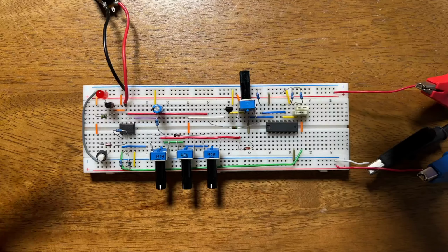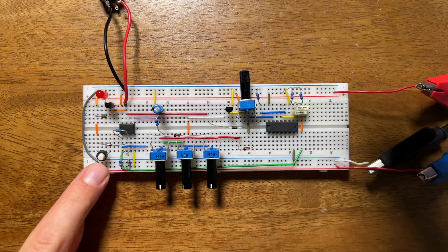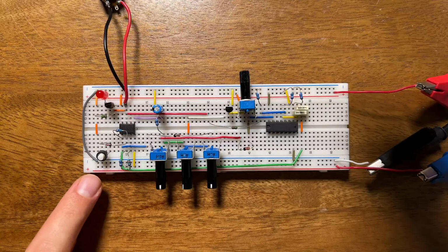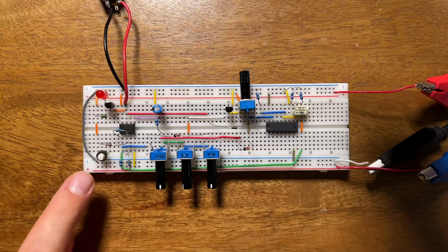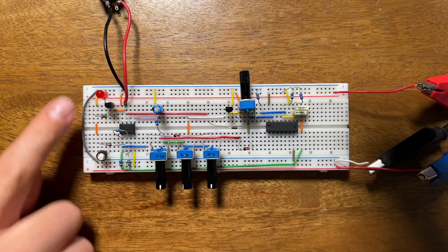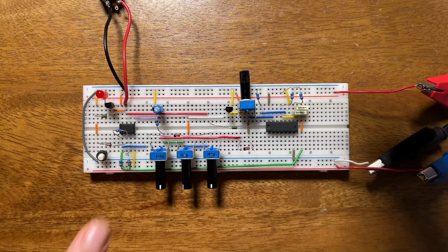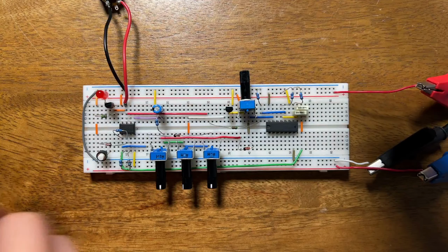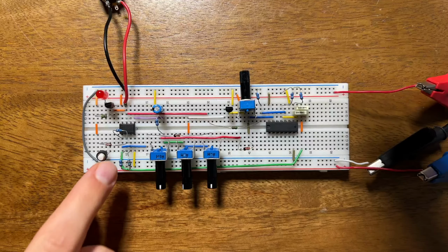Then I have wired it up to my modular, and over here there's a little push button, and this push button acts exactly like the push button that I've just shown you in the simulator. I've just connected it to 12 volts basically, and whenever I push this button, we apply those 12 volts to the input op amp, the one with the gain, and that fires the envelope. And here's what it sounds like. Let's hope it works.